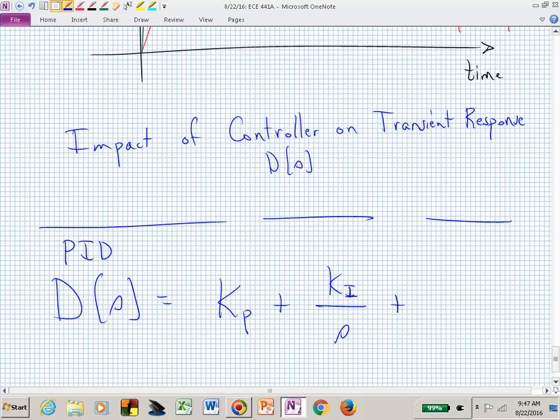The derivative part is now, what's a derivative? You're thinking slopes. It's anticipating where you're going or what you're doing. So the derivative term is helping you sort of predict what might be happening in the future, and that gives you better transient behavior qualities in your controller.